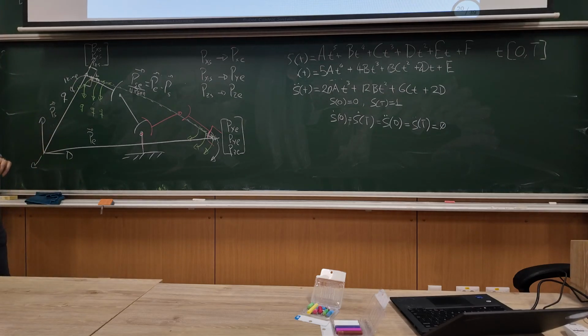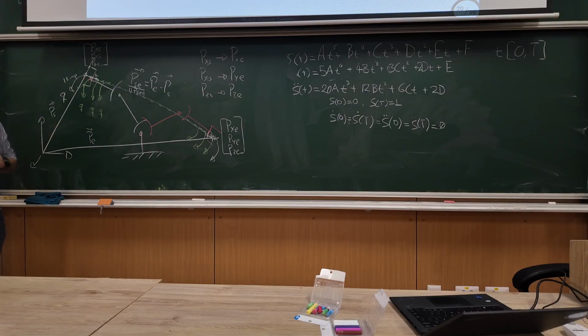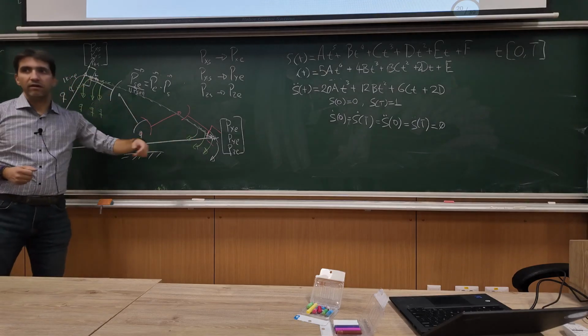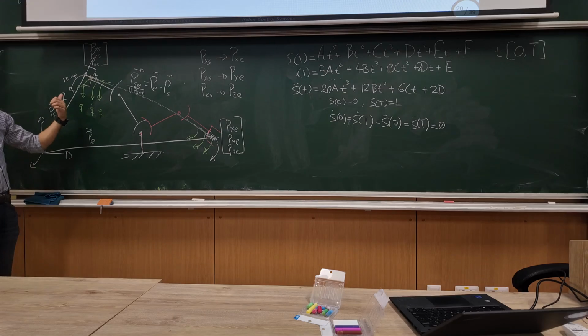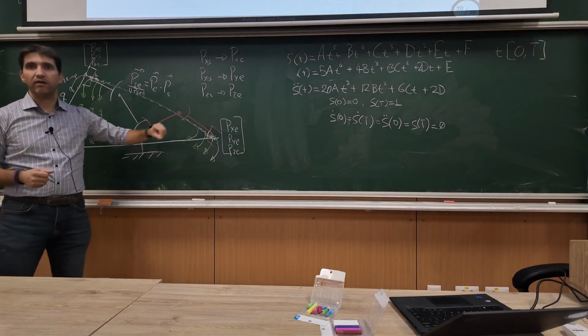Now, why I'm saying that this might be a little bit better than using the vector approach is that I can use my interpolator again to go from the starting values to the ending values, right? And because I can use the interpolator, I can use the linear interpolator or the polynomial interpolator. So I can make the transition from this point to that point smooth if I use the polynomial interpolator, meaning zero velocity and acceleration at the beginning and at the end as well, right?